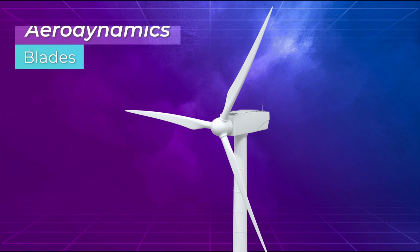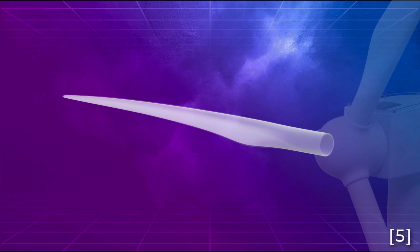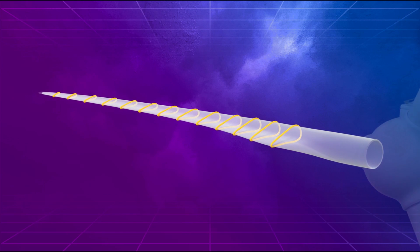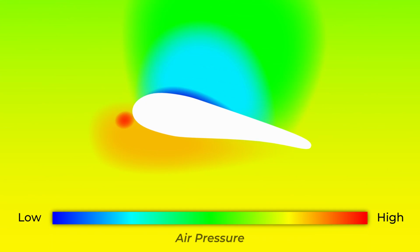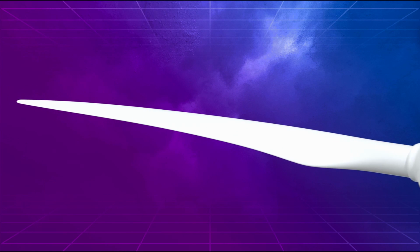Modern turbines use sophisticated aerodynamic principles to capture the wind's energy most effectively. Turbine blades are shaped a lot like airplane wings or propeller blades, using an airfoil design. Blowing air passes around both sides of the blade. Because of uneven air pressure distribution, pressure is higher on one side of the blade and lower on the other, and a lift force is generated, which acts perpendicular to the direction of the wind and causes the blade to rotate, starting the energy generation process.